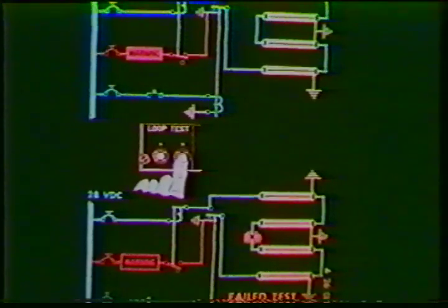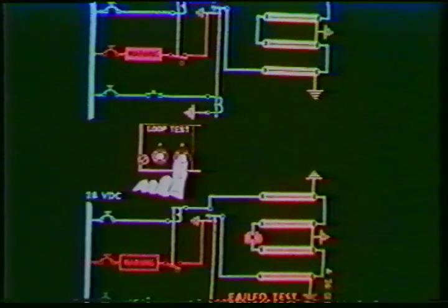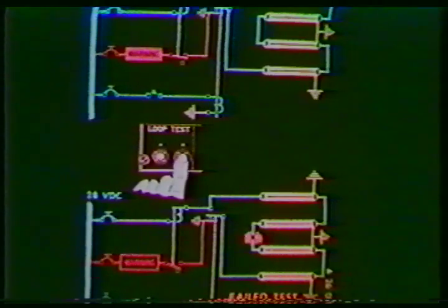This visual shows how the continuity of the entire circuit is tested. In the upper example of the test, the alarm circuit receives a signal only as a result of 100% continuity. In the bottom example, the open condition interrupted the signal flow from the alarm circuit.